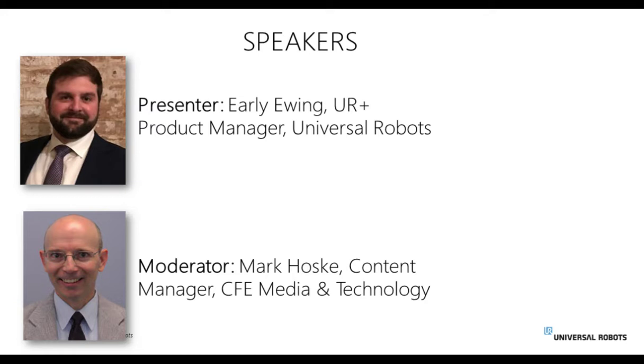Correct. I mean, typically that decision of whether to stationary-mount a camera or put it on the robot is dependent on lighting conditions and, in a lot of cases, cycle time. A stationary camera, since it's always bearing down on the area that you're trying to pick from, is always looking at that, so the cycle time might be a little bit faster. But once again, the fact that it's a cobot doesn't change anything in these applications. You can absolutely implement any vision solution that you can think of with industrial robots in a collaborative robot, oftentimes more easily.